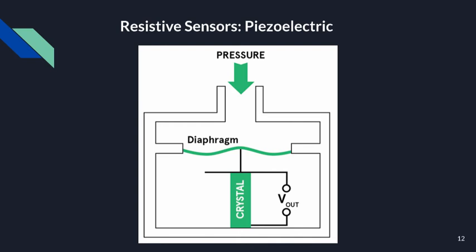In ultrasonic receivers, the signal amplitude is a sinusoidal wave, and variations in the ultrasound wave are translated into a sinusoidal change in the amplitude of the force applied to the piezoelectric transducer. In a similar way, the translational movement in a displacement transducer is caused by mechanical means to apply a force to the piezoelectric transducer.